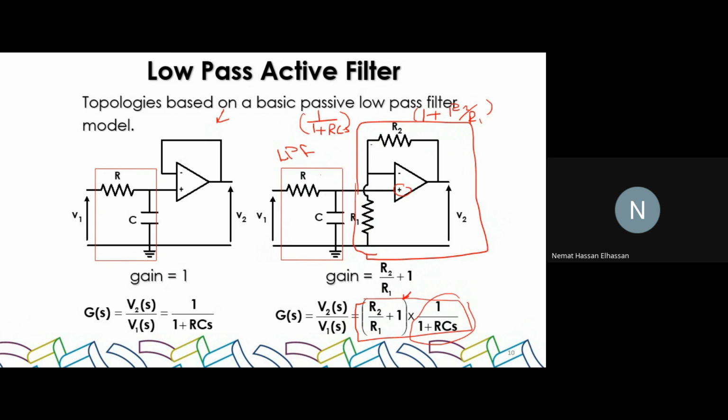If you compare it to the circuit on the right, R2 is equal to what? And remember, R2 will always be the resistance connecting the output to the negative input terminal. What is the resistance between the output and the negative input terminal in this feedback line? 0. There is no resistance. When there is no resistance, that means the resistance value is 0, right? The current is passing. So if R2 is 0, what is the value of R1?